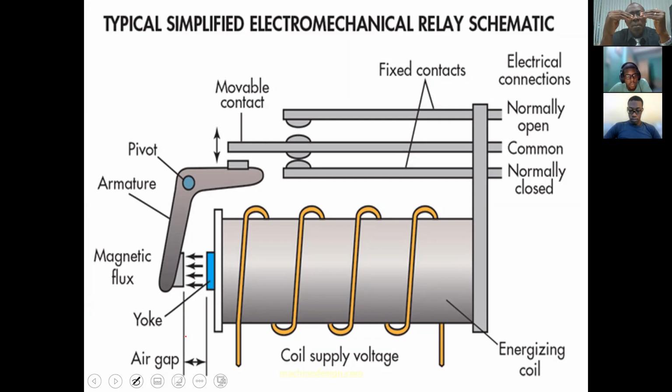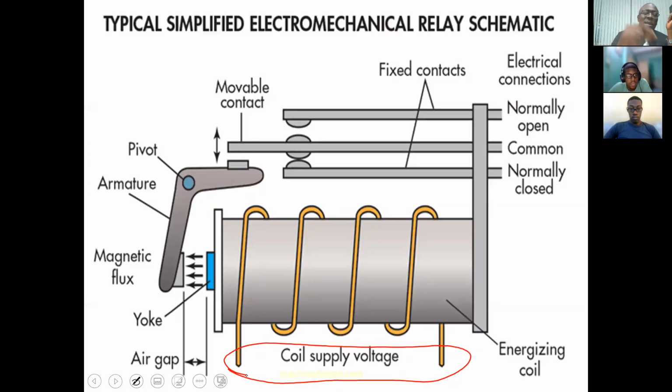The current from the CTs would come through that. And based on that current, you would then get a certain level of magnetic pull on the armature. Once that changes, then you're moving from pulling in. So it means that you're then going up, and you're moving the normally closed and then closing the normally open.